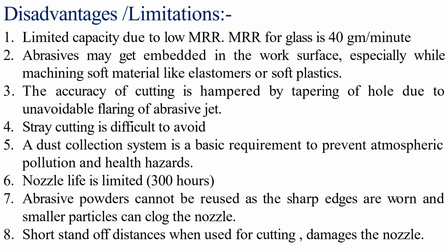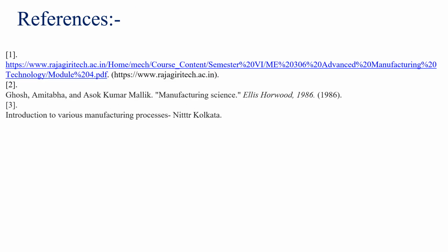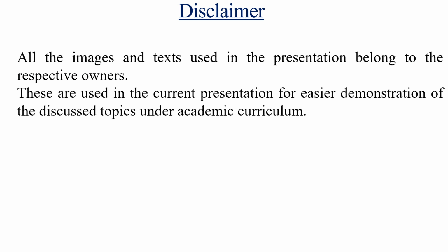A dust collection system is a basic requirement to prevent atmospheric pollution and health hazard. Nozzle life is limited, and abrasive powders cannot be reused as the sharp edges are worn and the smaller particles can clog the nozzle. A short stand-off distance when used for cutting damages the nozzle.